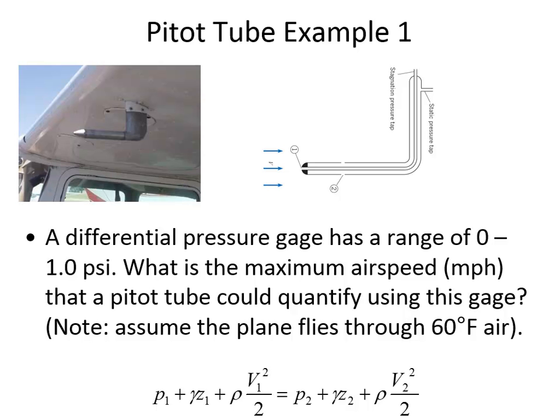A pound of force, lbf, comes from one slug being accelerated at 1 foot per second squared. So let's substitute that. 144 pounds of force is 144 slug times foot divided by second squared.